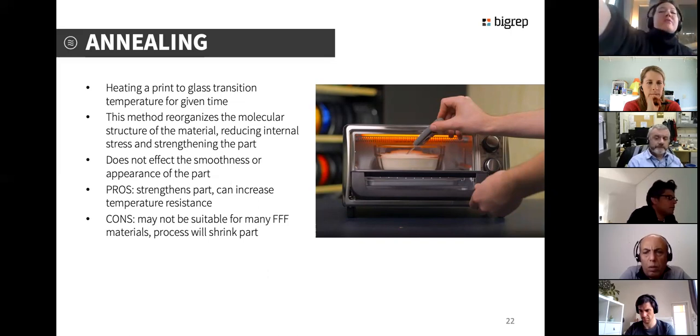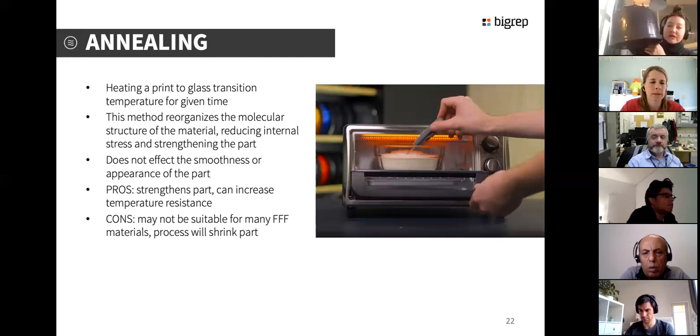So there was a sample we made some time ago for this. This is the hubcap of a student race car. Typically this was made with carbon fiber prepreg, you see here, that was put into an autoclave, and then this hardware attached to it here. Typically you would have an aluminum positive form milled, and then you would do the prepreg over top of it for the mold making, but that's really expensive. And since this was a student project, they reached out to us and we printed this mold form here.